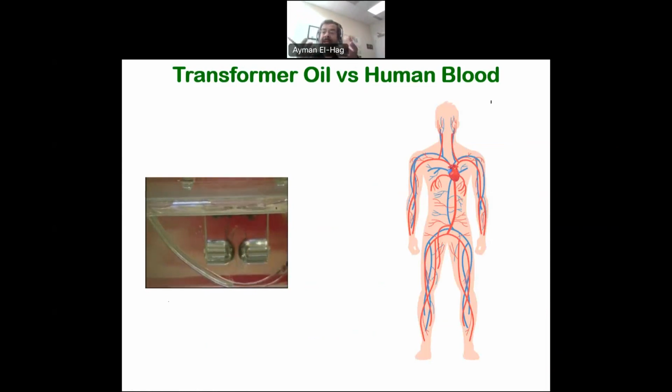Now we understand why we have this carbon: the oil itself is a hydrocarbon material. So when we have high energy, that will release some of the carbon. Now, carbon is not a good insulating material. So as we have more and more discharges and more aging from other factors, the oil will degrade gradually. We need to know the status of the oil to be able to tell about the life of the transformer. So we take samples regularly from the transformer oil and conduct several tests.